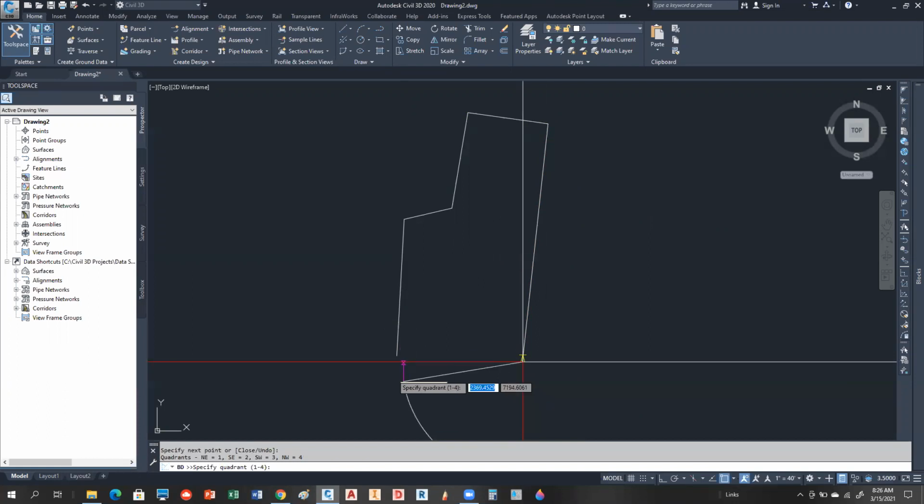If you're still working, if you're drawing that last line, just go ahead and draw it at the bearing that I show you. And then what we'll do is we'll zoom up and make sure that it's hitting. It probably won't be exact. Notice my bearing also says southeast on that final closing when you'd actually be northwest.